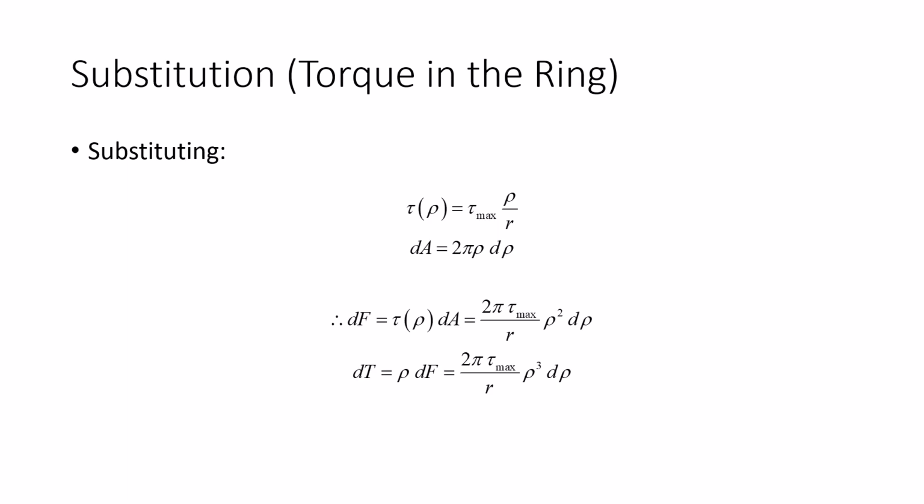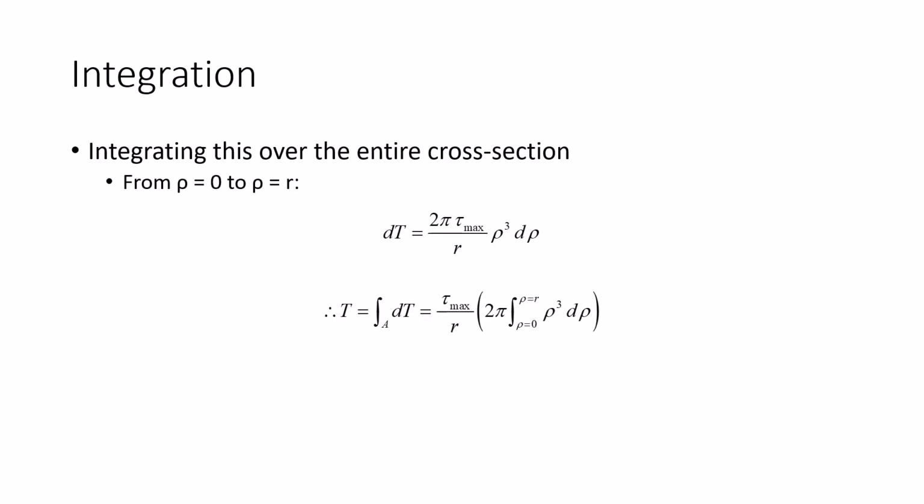So, here's our expression for stress. Here's our area. Here's this expression for force: stress times the area. Plug in my expression for stress. Plug in my expression for area. That gives the expression for torque. Now what I'm going to do is take this torque expression and integrate it.